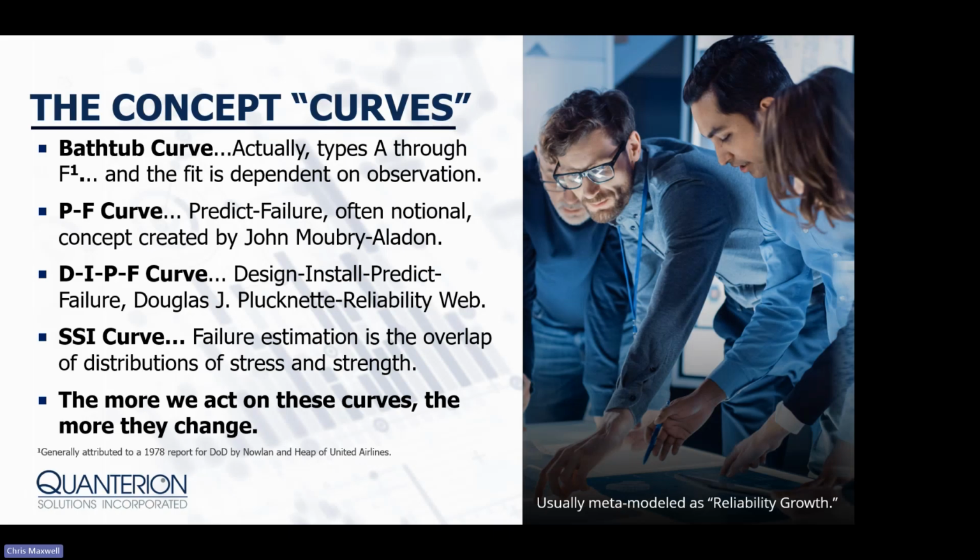Stress and strength interference. The more we act on these curves, the more they change. Sometimes you don't measure a bathtub curve for a part's lifetime relationship because you're already replacing it. You're not letting it get to wear out. That's especially true in the aircraft industry. They're not going to be leaving bearings in a turbine or a turbofan engine just to see how long it is before it wears out or breaks. They're getting them out of there before they get to the wear out portion.